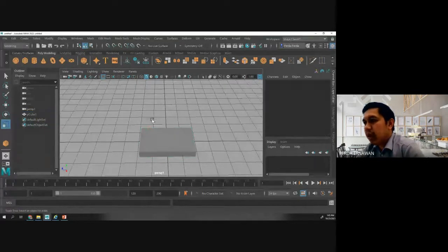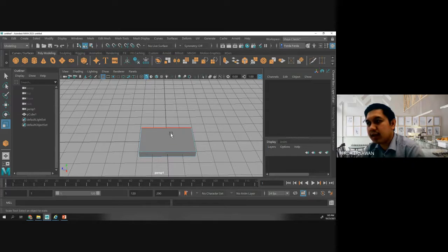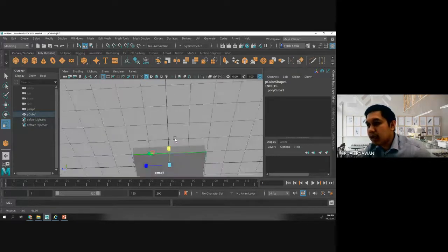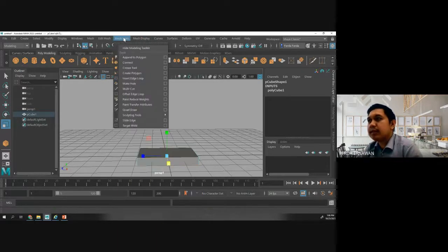Okay. Now we are going to implement the subdivision. Same thing in this 3D model. Number one, the way I select the edges, you have to look at here. First, I select the edges here. All right, this is the edges, right? So I select by selecting from the vertical like this. It means that I am selecting the horizontal edges, especially on this side. Okay. Next is select the connect.